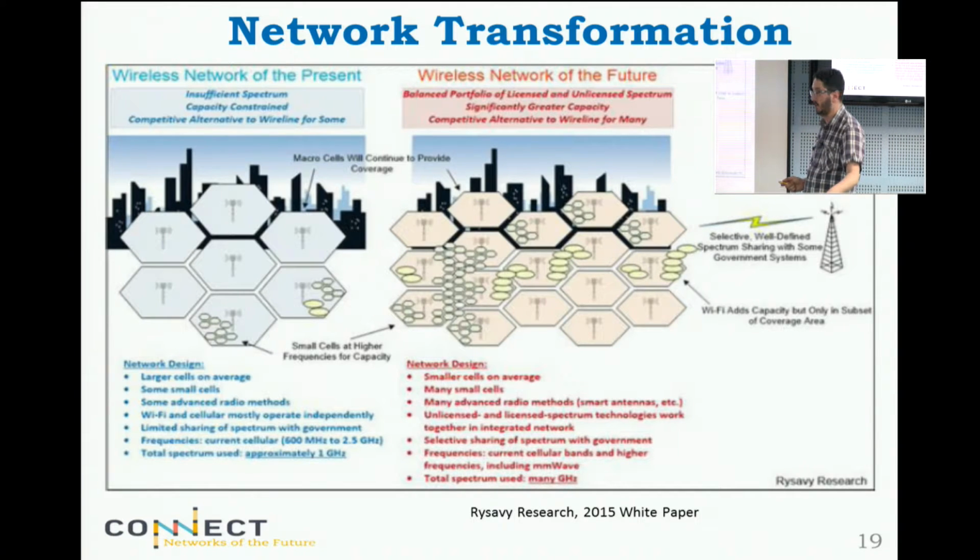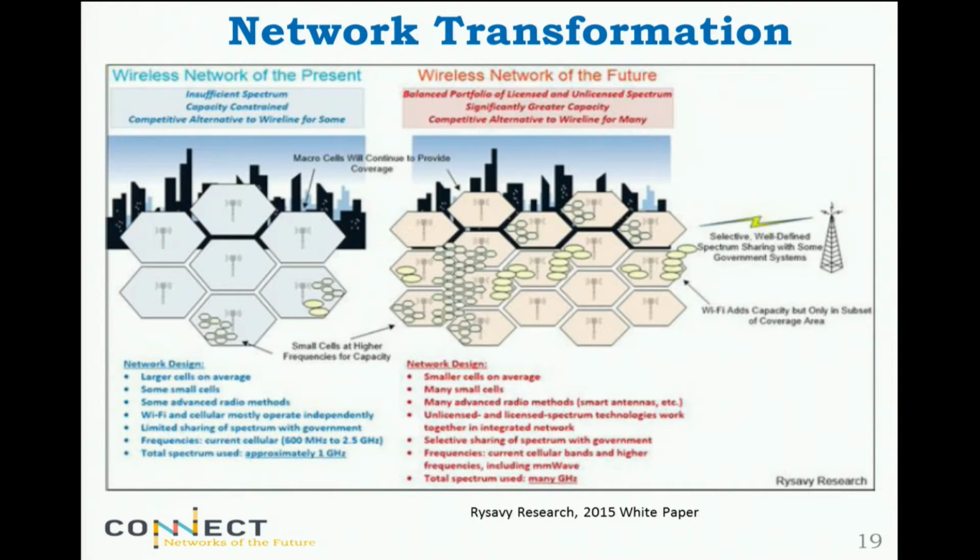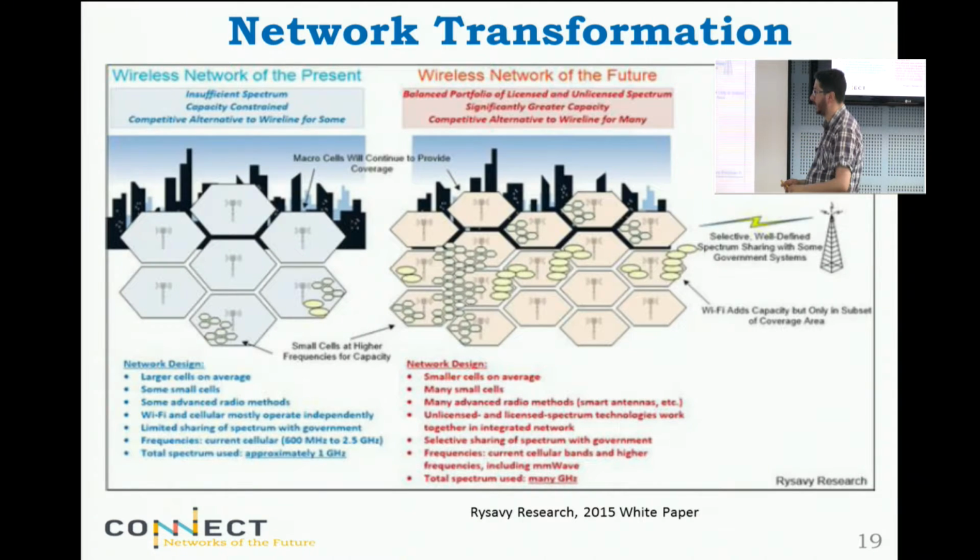We're going to see later in this course possible approaches to share radar bands. Radar bands are good because there is a lot of spectrum available in good regions of the EM spectrum, below 6 gigahertz, and they are not used very efficiently. Duty cycle is low, radar systems are very directive, and the SNR condition is very good. So it's possible to coexist with these systems without disrupting their operation, while still using a lot of band for commercial applications. There are a few groups working on this, not too many, and we are one of them. I'll come back to that in a few lectures.